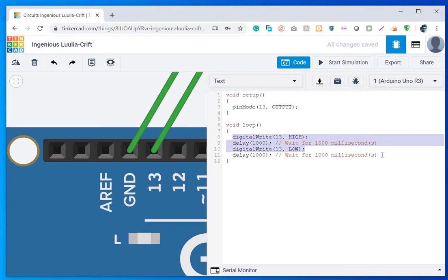And this is the loop function. This loop function runs continuously. It has to run continuously because when some changes come in the sensor, for example a light sensor detects light, it has to continuously scan the changes in the sensor. That's why this loop function needs to run continuously.